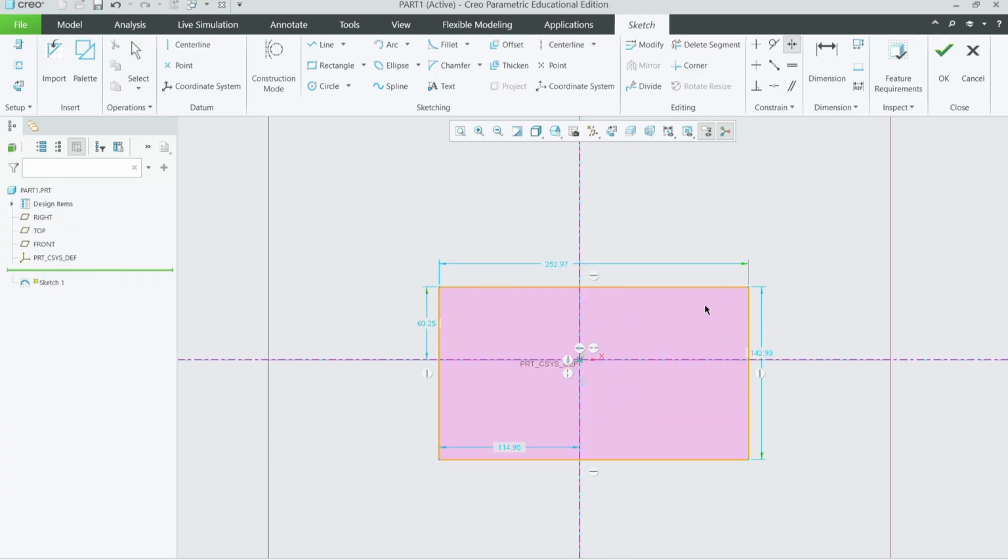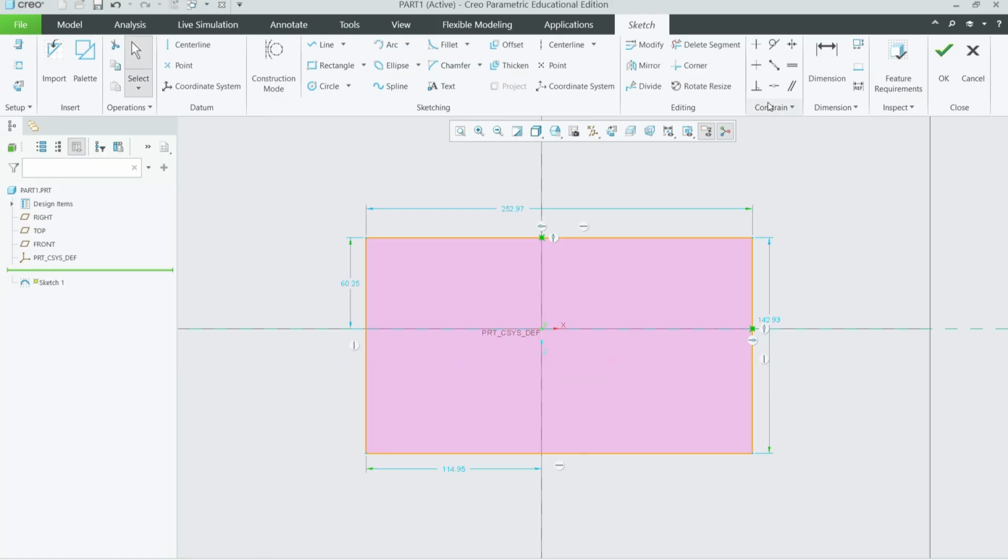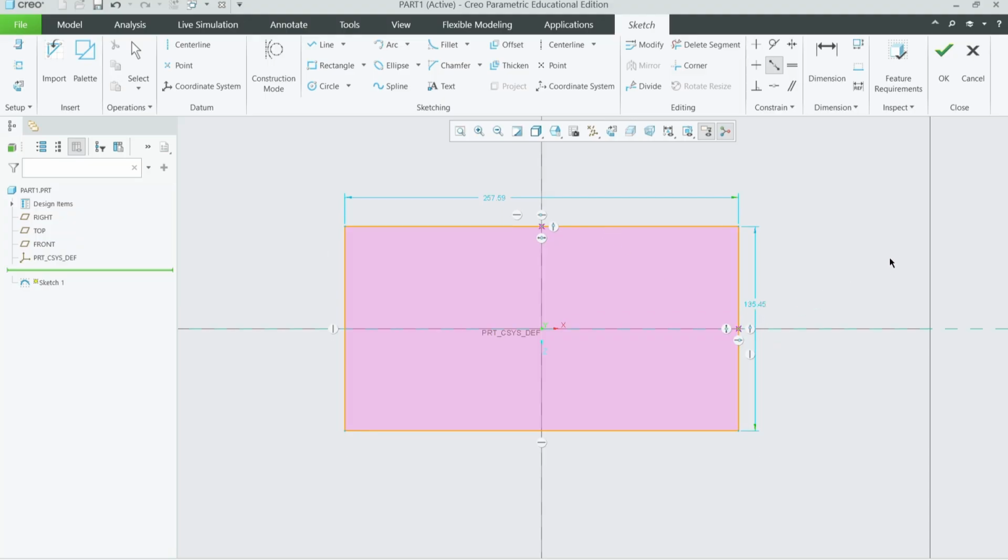using. Next is a pretty clever way to constrain a horizontal or vertical line, say for example in this case in a rectangle, is by sketching a point on that intersection between the center line and the horizontal, or the center line and the vertical lines on the rectangle, and then using that midpoint constraint to make sure that that line midpoint is that point that you created.